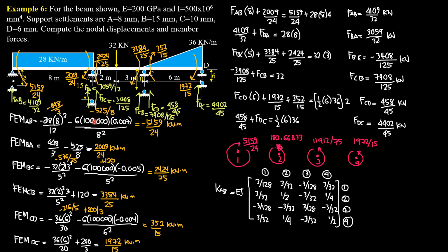The sideway moment formula from slope deflection equation, remember, moment is 2EI over L quantity 2 theta near plus theta far. Theta near, theta far set to 0, so we have purely relative displacement due to side sway. So minus 3 delta over L. So 2EI over L quantity negative 3 delta over L is negative 6EI delta over L squared. So that's the side sway moment formula.